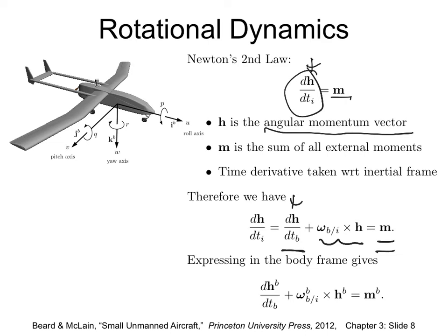For right now, we are just saying, okay, let's apply a torque along the x-axis, along the y-axis, along the z-axis. So this equation can finally be written in the body frame like this, because let's say all the external forces we are somehow able to compute in the body frame. Even if they were not in the body frame, we can translate everything to the body frame.